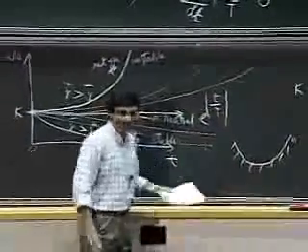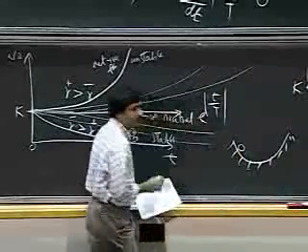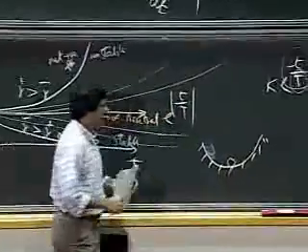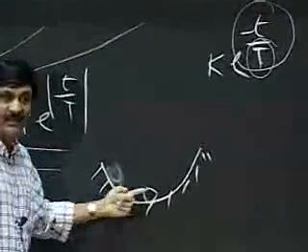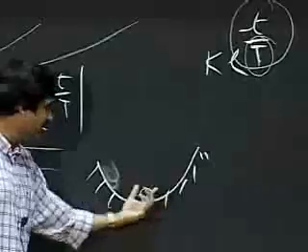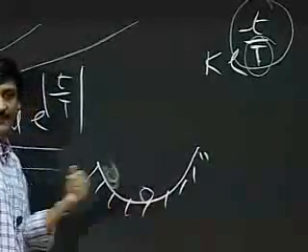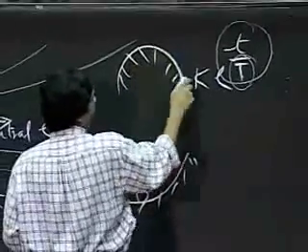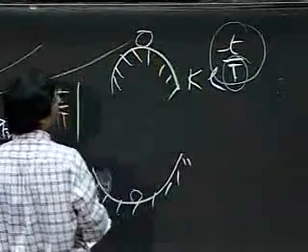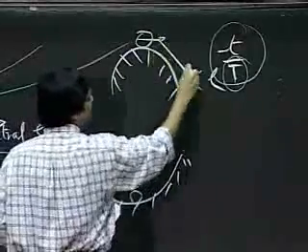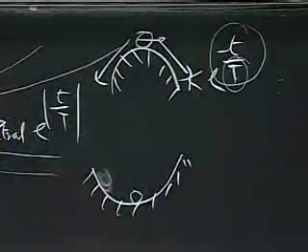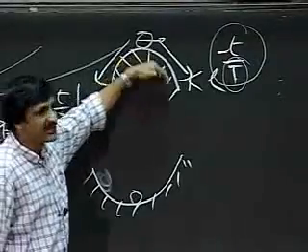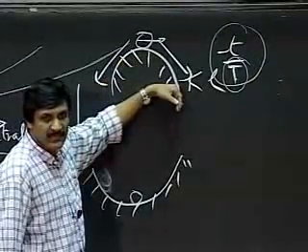let's add a physical well of this sort and add a ball in there and let the ball go, then the ball will come down here and settle down in a stable state. Any small perturbation of the ball will get it to come down and settle down here. Okay? The unstable situation is this situation where I have a ball sitting up here where any small perturbation will get it to zip down to a positive rail or to the negative rail. Okay? So this is an unstable equilibrium situation.